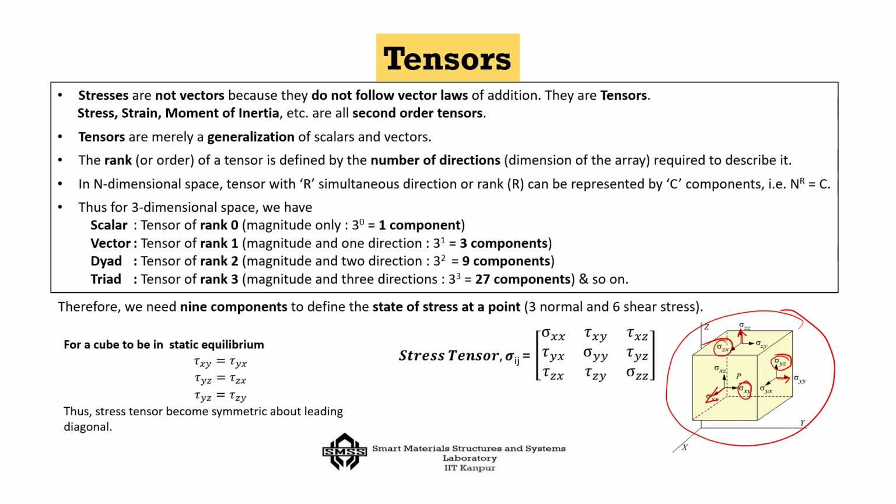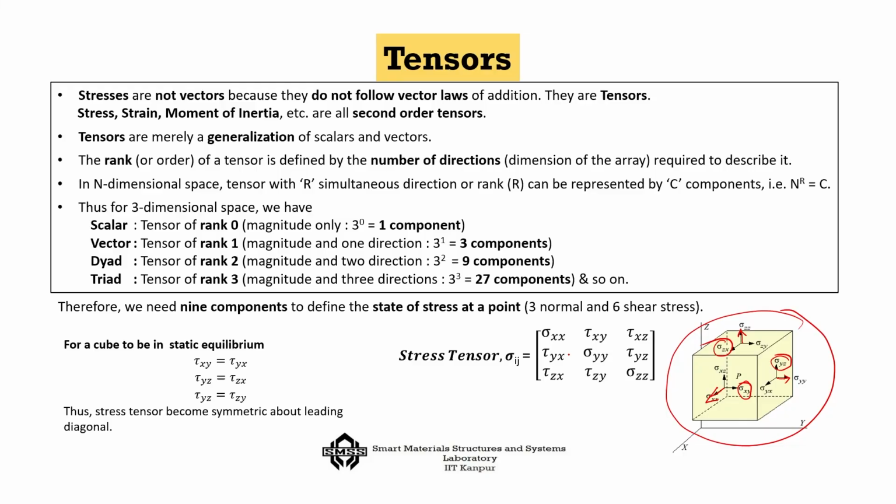So, if I have these other components of stresses also, then we need to express the generalized Hooke's law, where we need to express the stresses in terms of a stress tensor. That is what we have done here: in the stress tensor, the diagonals are all the stresses along the axial directions, and the off diagonals are all shear stresses. So, together this creates a stress tensor.